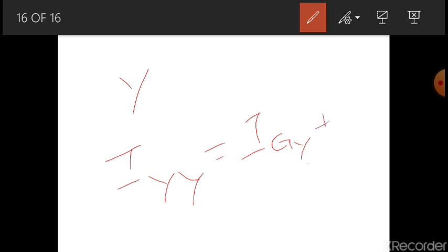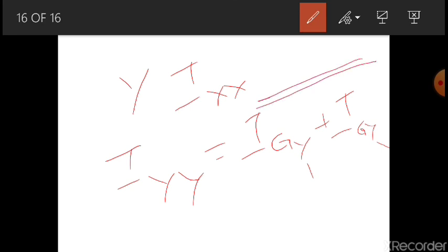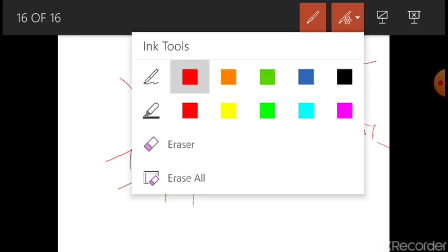But in the same case, when you are calculating Ixx, the formula remains the same as in the above question: Ig plus A into h squared, where h is y bar minus y, to the whole square. That is the difference in the solution, nothing else, if it is symmetrical in the case of I sections.